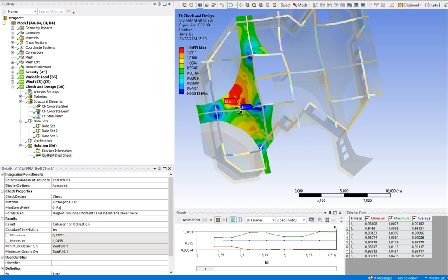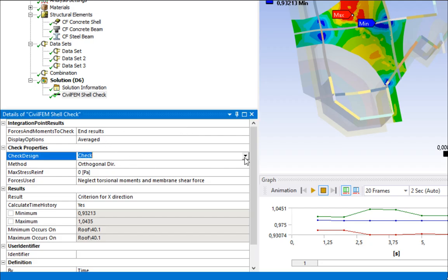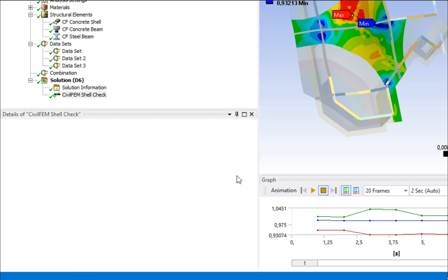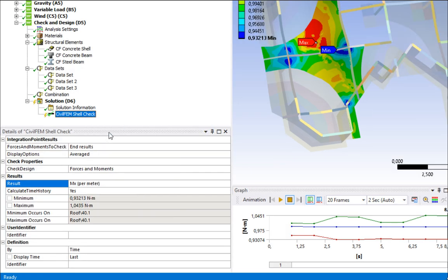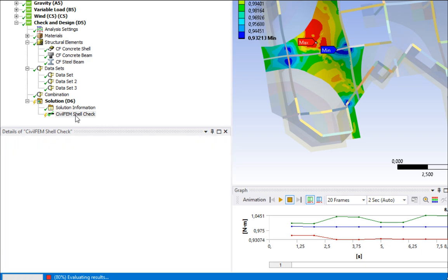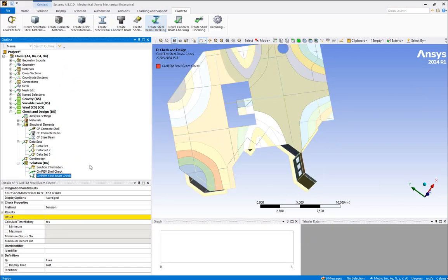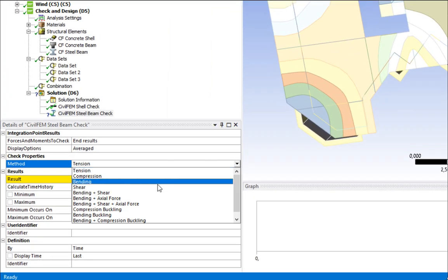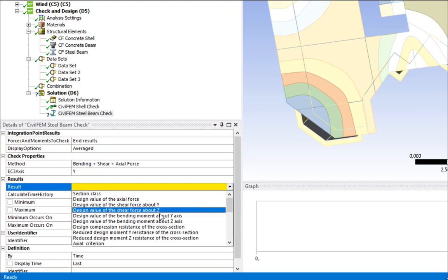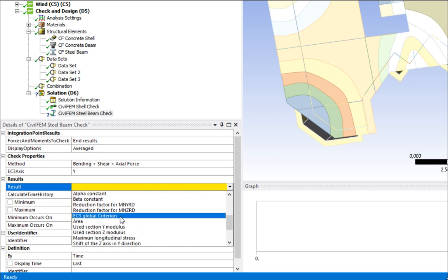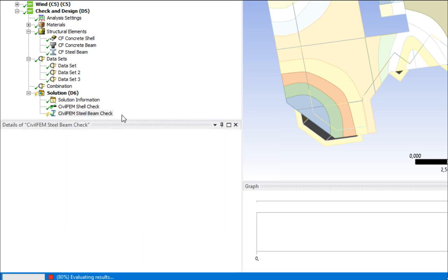Thus, we can use Ansys Mechanical tools to export the results or evaluate the maximum across all combinations, to visualize the checking envelope. We can also evaluate the forces and moments obtained from the combinations, which are used for the checking and design. The checking results include both the overall criterion, which defines the ratio between the design forces and the section capacity, and intermediate standard results,